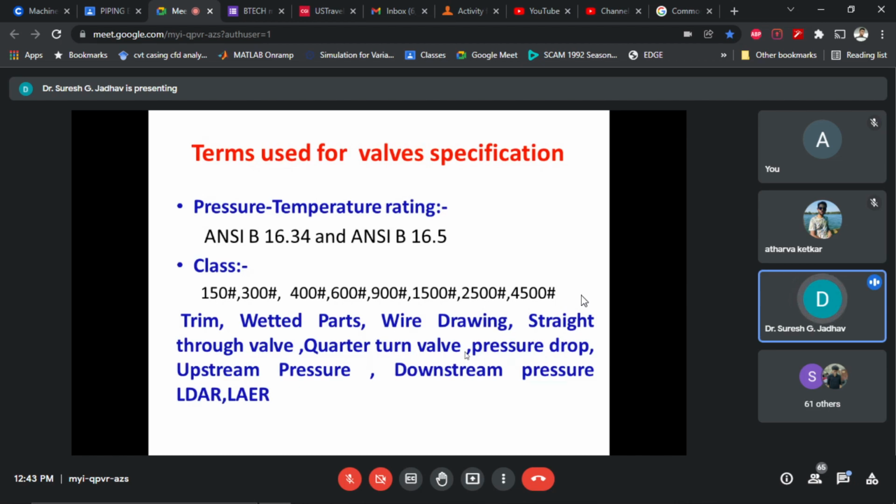The ice formation on the wedge will obstruct movement, thereby increasing the leakage through the seat.